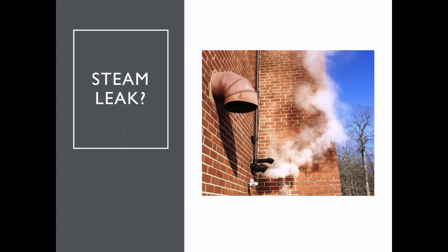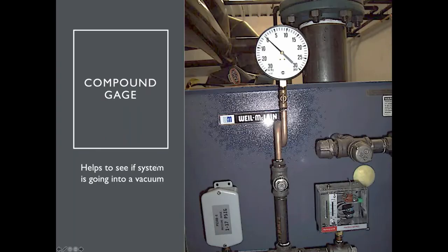And I looked at this and I'm thinking, wow, unless he gets his system repaired, mine's not going to last any longer than this. So I explained to him that the system is not supposed to have the steam coming out in a plume like it is. It's supposed to have just a little wisp on the low pressure steam boiler.